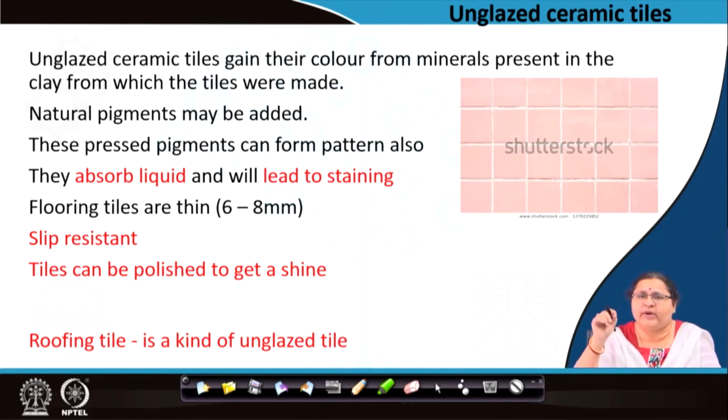It is the water absorption, where you are using it, the place where you are recommending it. That is very important. So if you know where you are using it, whether that area is a dry area, then no need of thinking of water absorption. If it is a washroom, you have to think of water absorption. If a lot of people are moving through it, you have to look into its strength. As you had seen in the first picture, a set of urinals on the wall. No one is going to walk on it. So it is a wall tile. Their compaction may not be to the extent of the floor tile. So all tiles are not made in the same way. Not all are facing the same kind of pressure. So you have to choose knowing all these points.